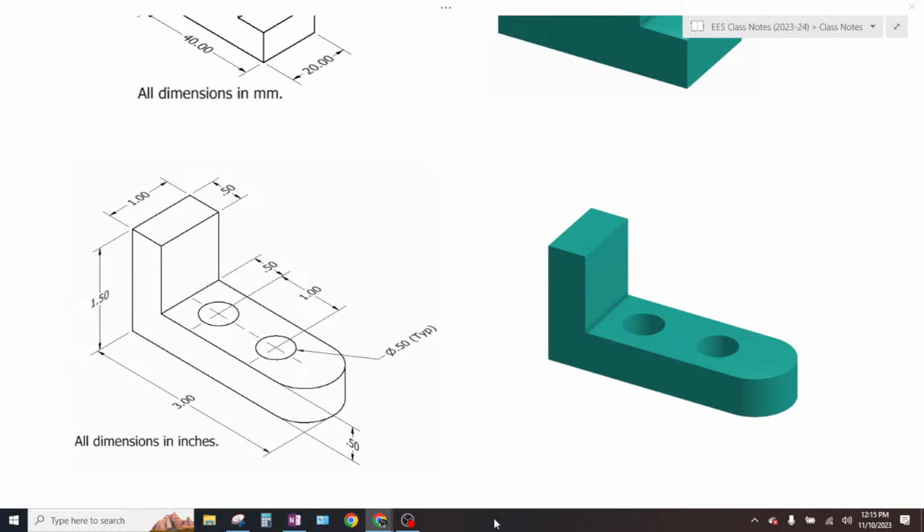Now, if you separate the teeth, you'll notice that this thing sticks out. That is on purpose. That is what you use to measure the depths of holes. So you actually have three ways you can measure stuff.